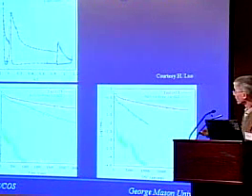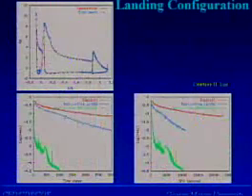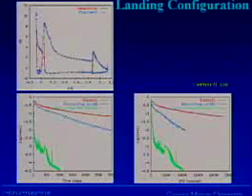So you can see that you actually reproduce the physics faithfully. And if you take an ordinary scheme with explicit time stepping, you can compute for days on end without reaching anything. And if you combine GMRes with LUSGS as a preconditioner, you can get very quick convergence. So that led to, again, a factor of 10 or 15 in speedup.